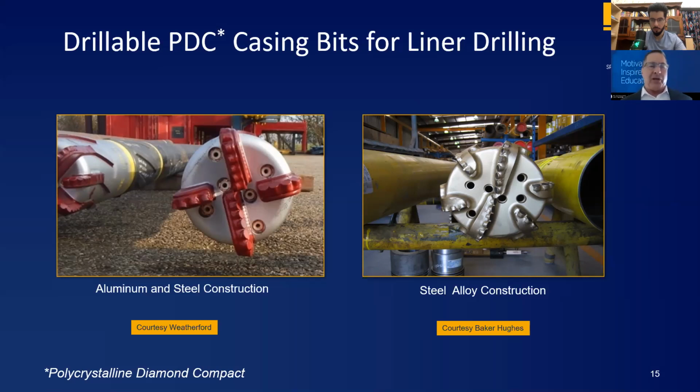So we like to look at sonic logs and density logs. Sonic logs, typically transit time readings greater than 65 microseconds per foot, are usually soft enough formations that a casing bit can drill these. Once you get transit time readings less than 65 microseconds per foot, you're looking at formations greater than 20,000 PSI unconfined compressive strength. This makes the design of the bit more complex.